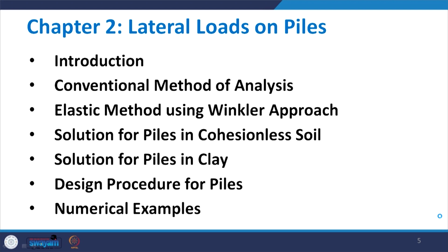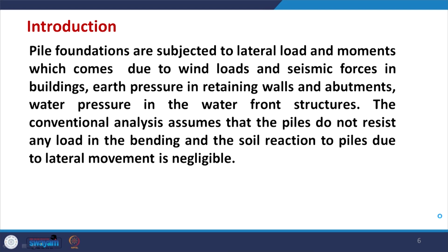Let us start with the introduction on lateral load on piles. You may be aware that pile foundations are subjected to lateral loads and moments which come due to wind loads or seismic forces in buildings, earth pressure in retaining walls and abutments. It could be due to water pressure in waterfront structures or offshore structures. What we are going to discuss is not only applicable during earthquakes, but equally applicable for any type of lateral load, whether due to wind, water pressure, or earth pressure on retaining walls.